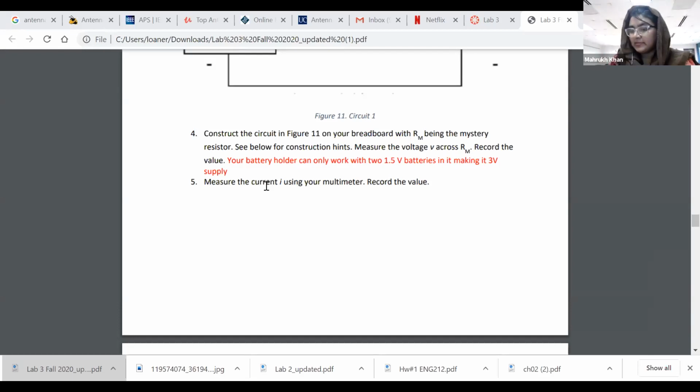Yes, it's about tolerance. If my resistor is 1K and its tolerance is 5%, it means that it can change its value higher or lower by 5%. So if it is changing its value towards the lower side, then it allows more current to flow. But if it is changing its value towards the higher side, it allows more voltage to show up. Okay? Make sense? My battery started doing the thing where it gets hot also.